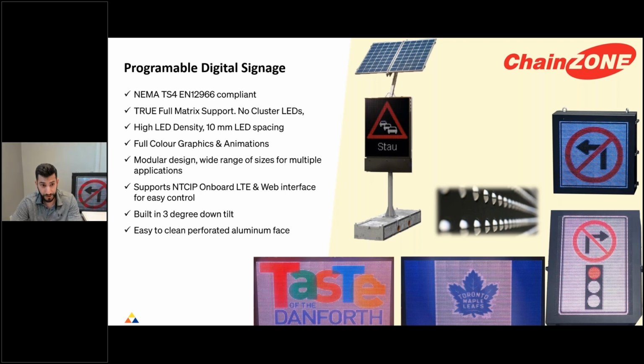Additionally, these boards can be NTCIP controlled. They support an onboard LTE web interface and NTCIP control out of the box. You just have to connect it to one of your modems. And that means you can monitor the sign remotely. So if anything does happen, you can get a failure alert through the modem, or you can just monitor the sign to make sure that it's posting the correct messages, or you can remotely upload messages to the board should you want to change the restriction that's being presented.